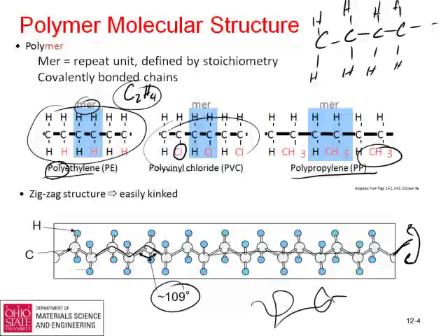The covalent bonds do not go away except at very, very high temperatures. But these secondary bonds, like most secondary bonds, this isn't so different than what happens with water. Water evaporates at 100 degrees C. Most of these polymers become noticeably very, very soft also around the same temperature, around 100 degrees C, and we'll see that quantitatively as we go through this lecture.